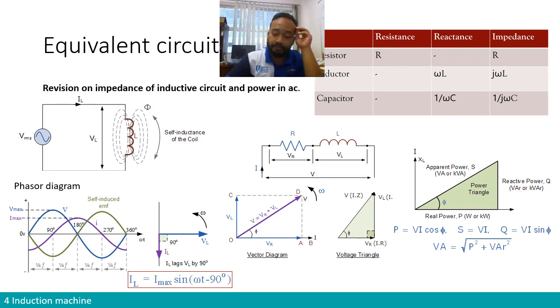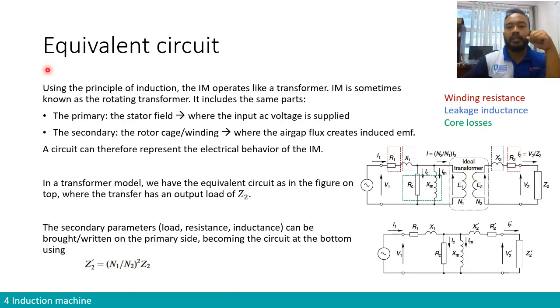by the stator. So by now you understand that the operating principle of an induction machine relies on the principle of induced current. In the stator you have an AC current, and the rotor is basically a passive component. It's not supplied with electricity. It's just put in the middle, and the magnetic flux goes across it, and the variation of magnetic flux inside the rotor will create the induced current. So this principle of operation is exactly the same as what we have in a transformer.